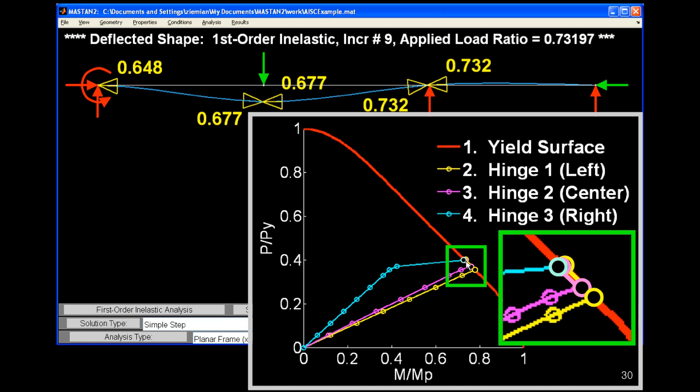Okay. So here's the first question. Can you have a true plastic hinge if the member is non-compact or slender with respect to flexure? Yeah, very, very important question. So when we start going with this material nonlinear analysis, we've got to make sure that our cross-sections are compact, that they can fully yield, and not only can they fully yield, they can undergo a significant amount of rotation before they will reach that limit state of local buckling or whatever the attendee was asking about. So it is very important when we do an analysis like I'm showing you that the cross-section itself is stocky enough to undergo those large deformations. And the defining element is, again, assuring it meets AISC's compactness requirements.